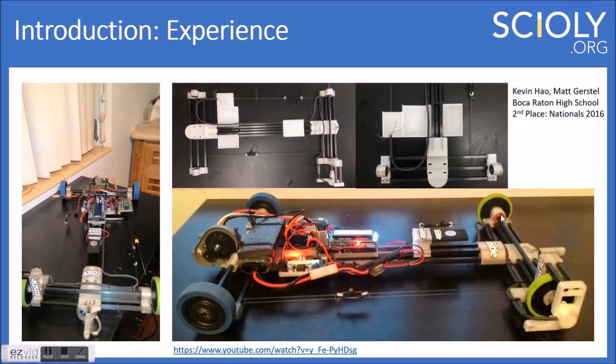You can see our axle was carbon fiber. It's this carbon fiber rod that was fitted into these ball bearings here. And we did use Bainbot wheels for all 4 wheels. You can see this laser pointer in the center here that was used for aiming, which has played a huge role in our success. The rotary encoder at the side here keeps track of axle rotations. And that's how we figured out the distance we were at and controlled that with the device.